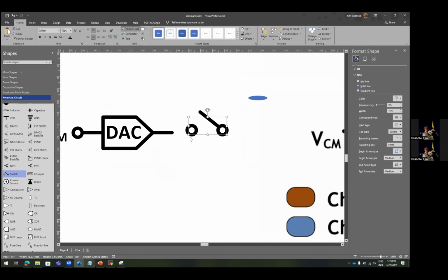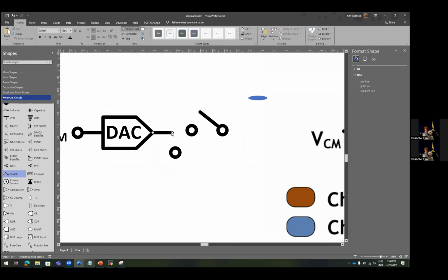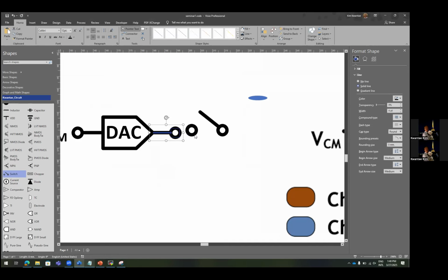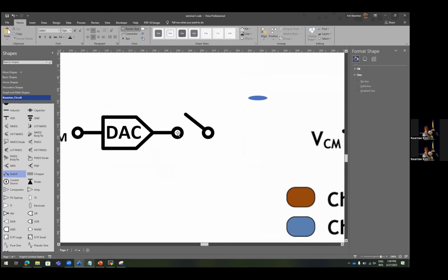For doing that, you can click again within this selection, like this. Then we can select this circle and copy and paste, or you can do Control drag, right? Because these two circles are equal to each other, you can make this alignment on the bottom side. Now it's aligned. The center point of this circle is aligned to this line.